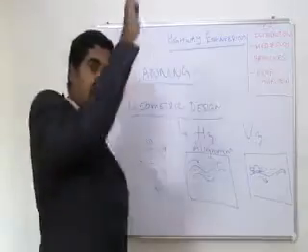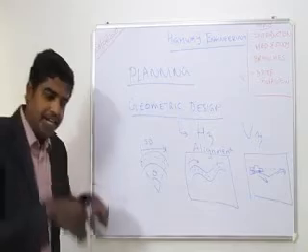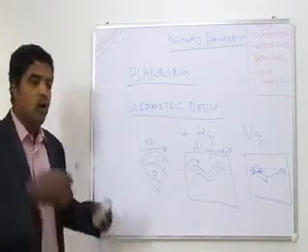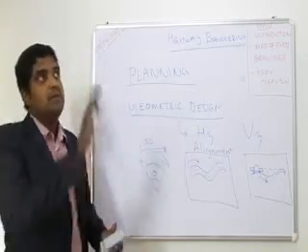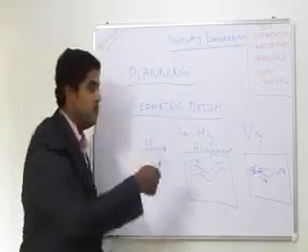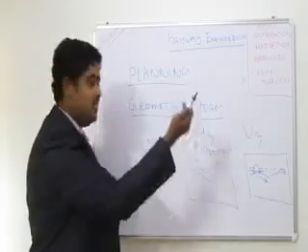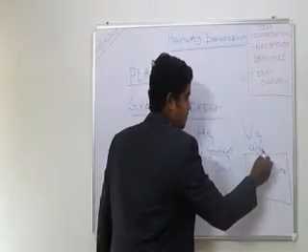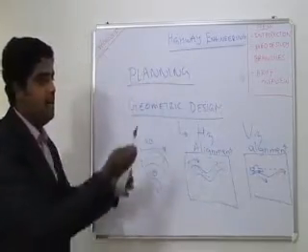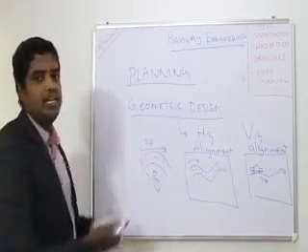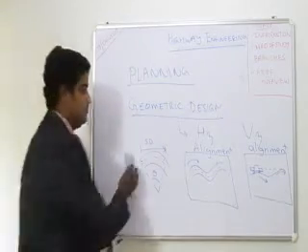Going up the gradient is known as the summit curve, and going down is known as the valley curve. How steep the slope or incline gradient should be, studying all those things comes under vertical alignment. Horizontal alignment and vertical alignment are the main core in studying geometric design.